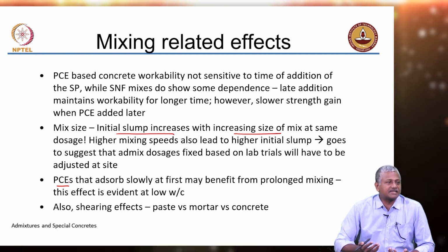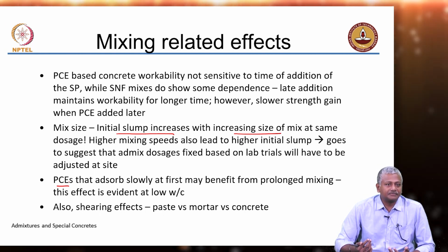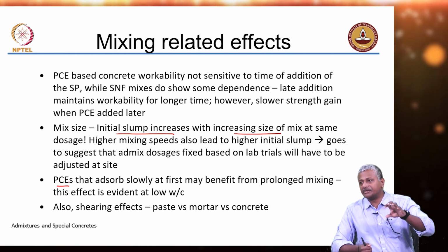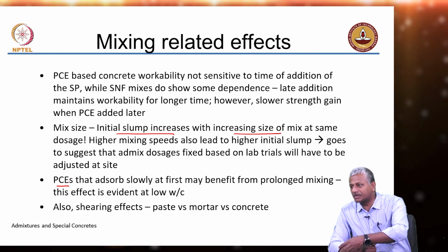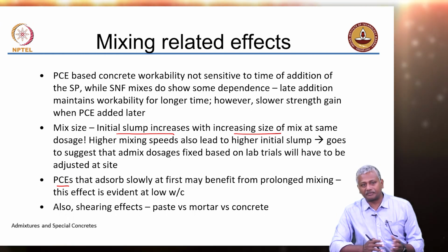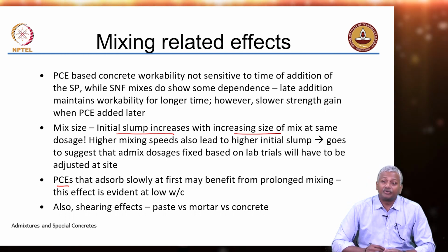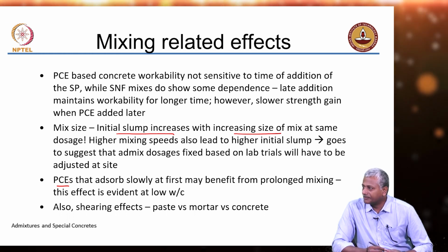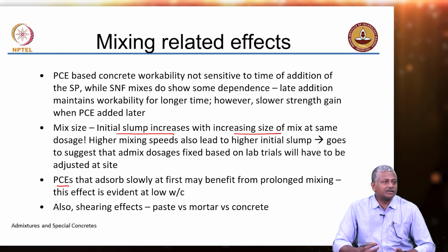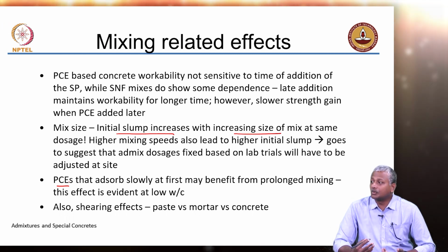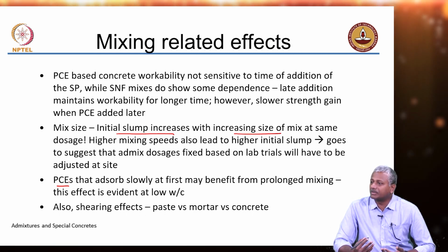You want to make the mix as homogeneous as possible, right? It should not fall off in chunks on one side and then start flowing on the other side. It has to have a uniform slump. Uniformity of concrete should be good. For that, mixing longer is obviously important. But if you mix longer, it doesn't segregate. If you mix longer, it reduces the productivity of a plant, right?